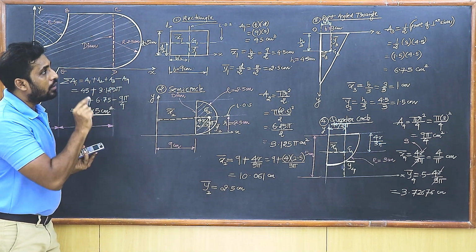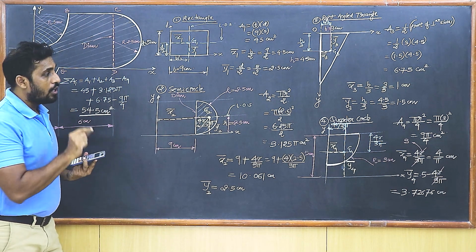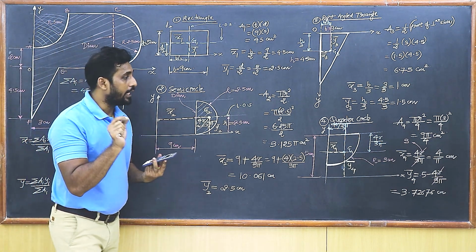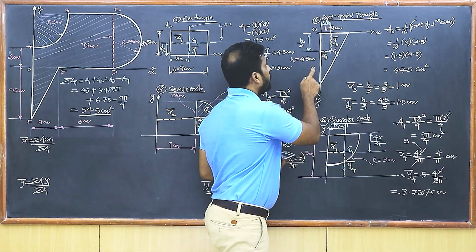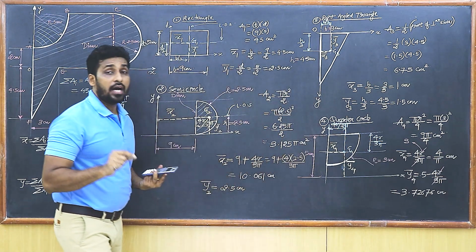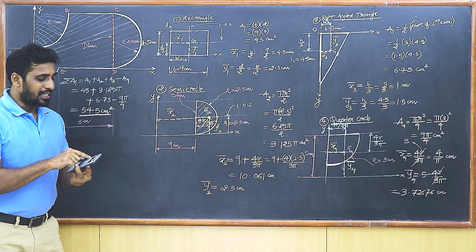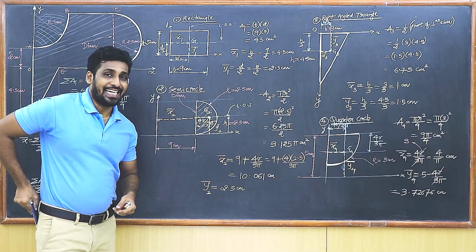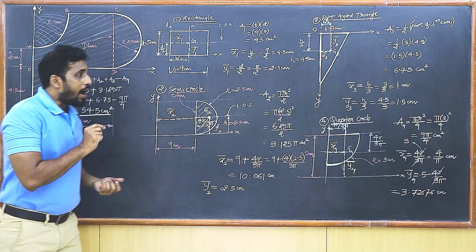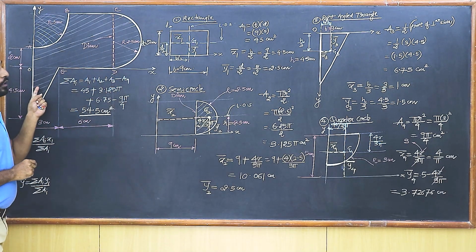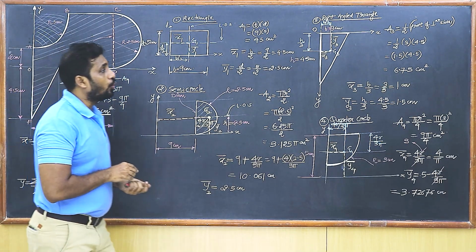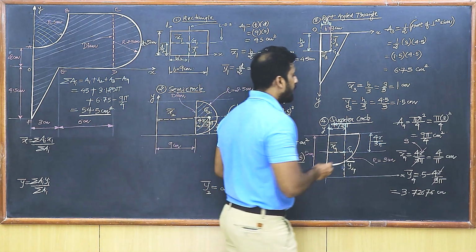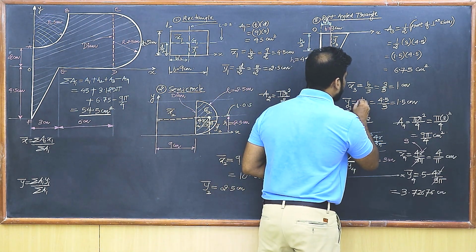So students, over here you need to understand, only for the right angle triangle, observe carefully, I have done a very small mistake over here, and that mistake is that for the right angle triangle, y3 bar is going to be negative. So can you understand there can be a big blunder if you do not pay attention. Y3 bar is going to be minus h upon 3.